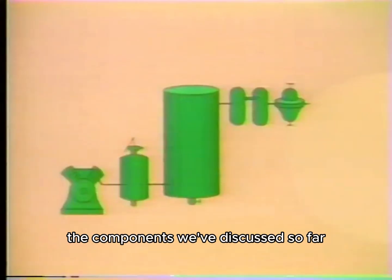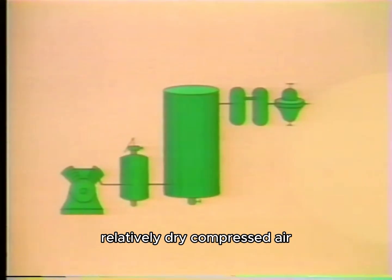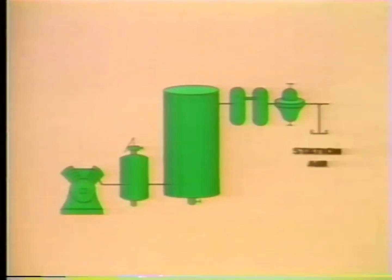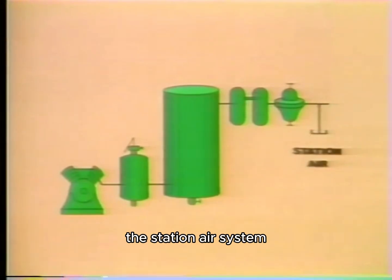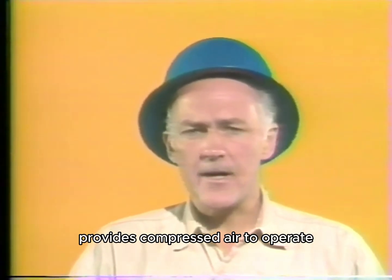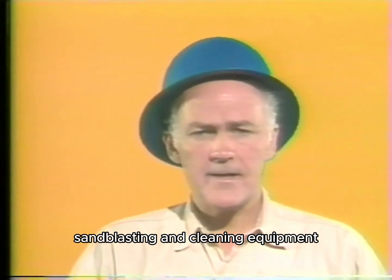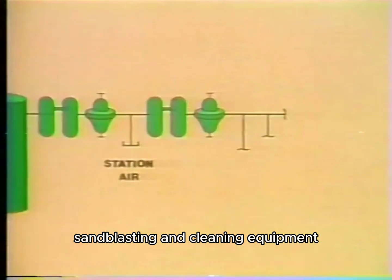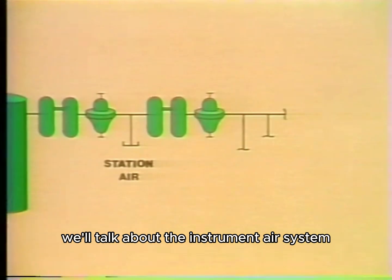The components we've discussed so far function together to provide a constant, relatively dry, compressed air. These components make up what is often referred to as the station air system. The station air system provides compressed air to operate, for example, pneumatic tools, sandblasting, and cleaning equipment. It also supplies air to the second air system we'll talk about, the instrument air system.